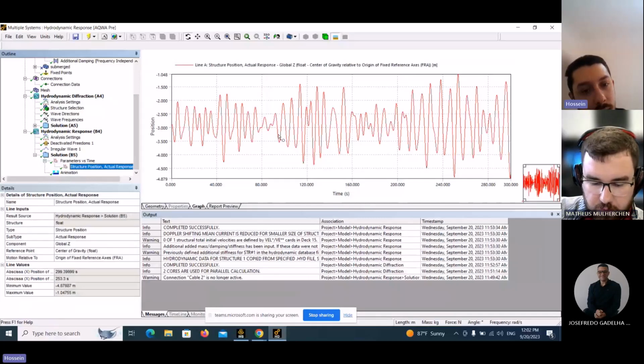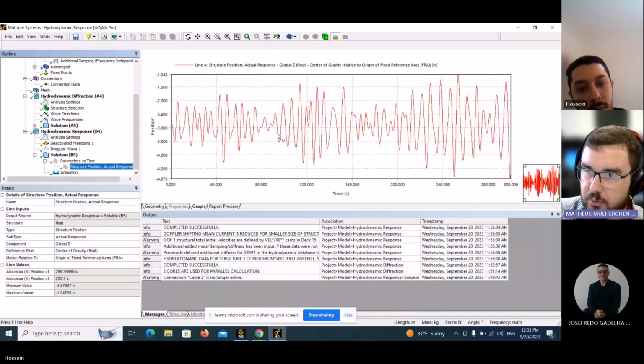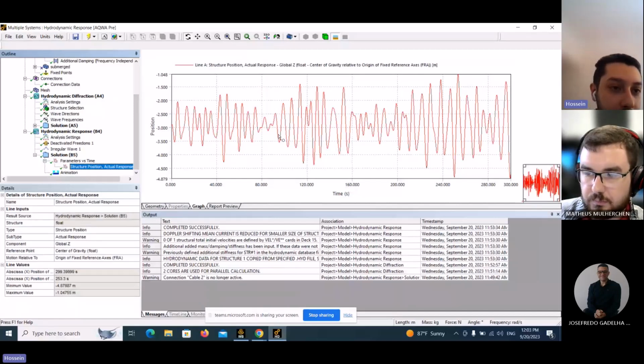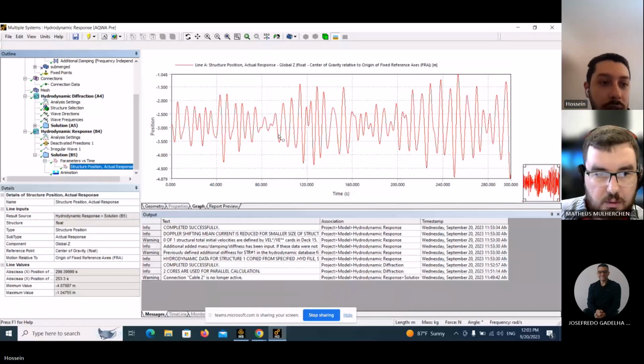Another question about the geometry itself. When you are drawing it on SpaceClaim, you have to turn on the option to share the topology. Do you do that for each part separately, or just the component that has both parts in it? We did it for each component separately. As you can see here, we have two components. One is the float part.